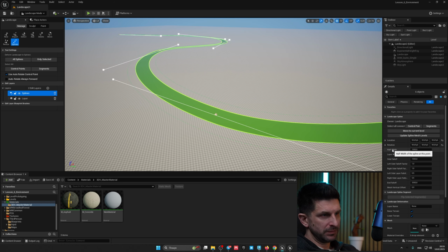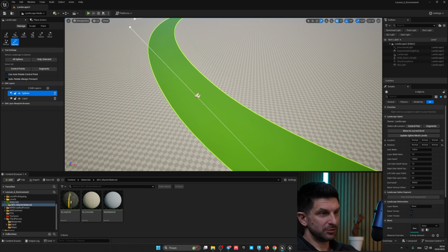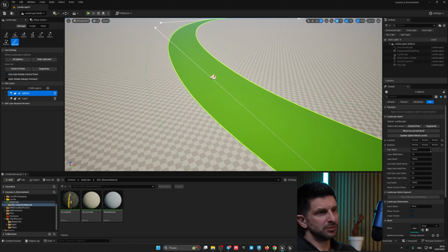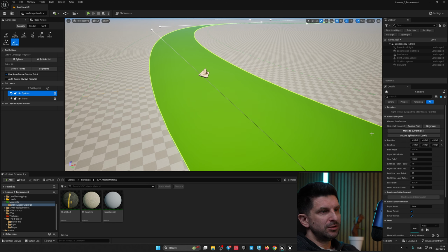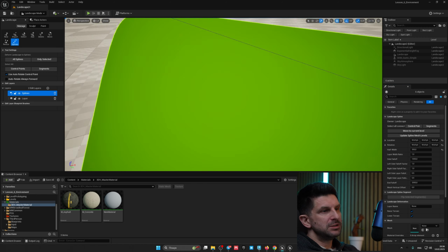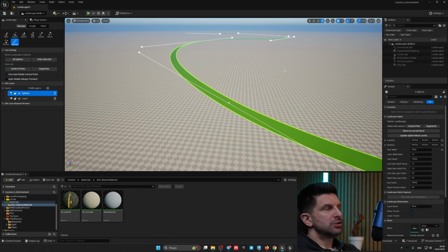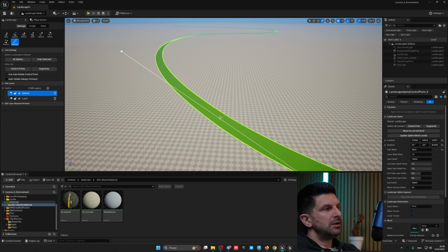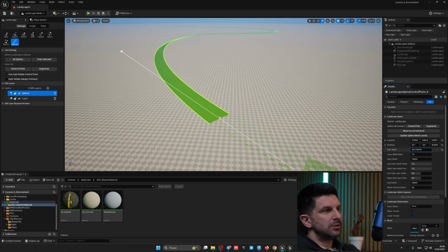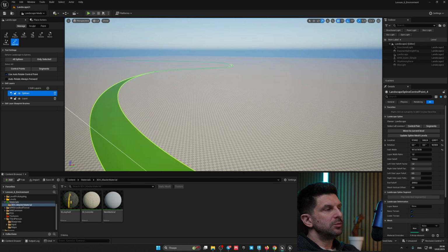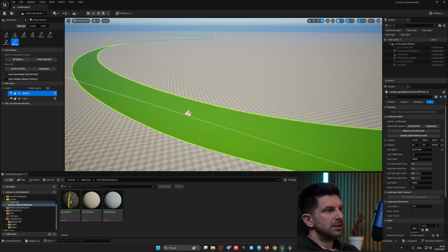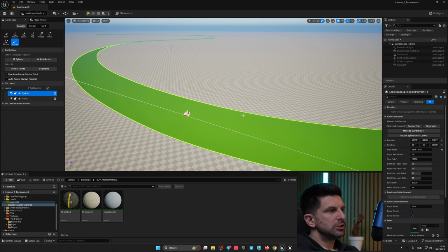And we can specify here the half width, meaning half of the width. In this case, it is set to 10 meters, and that's the half. So if our road is a normal paved one, let's say 6 meters wide, we should write 300 here. Then it will be of normal road width. Well, a 6 meter one is implied. There you go. And look, there is an option if you are making, for example, some path in the forest, not paved. You can select one point and adjust it separately. That is, you can increase the width at this point, and further on, it will be narrower at the other points. This can also be done. Well, maybe someone will find it useful.